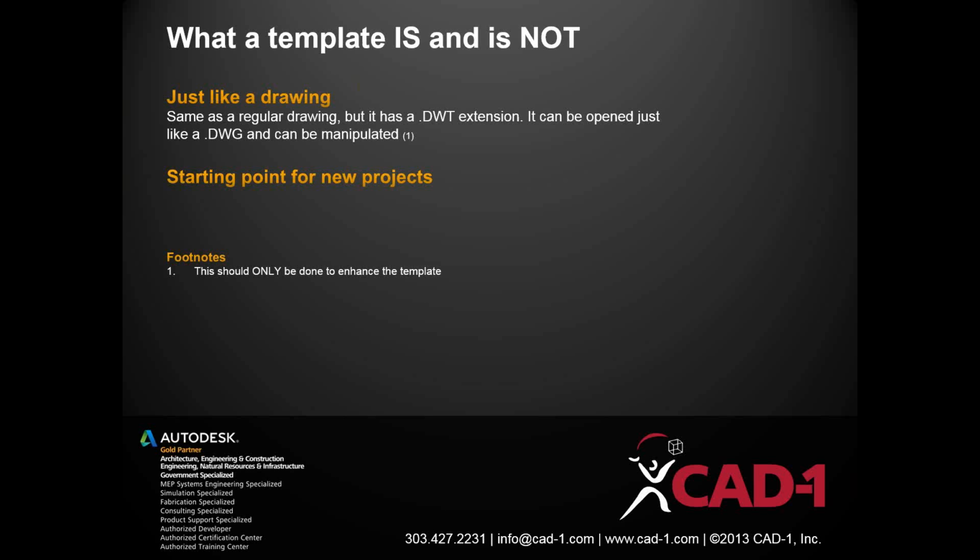Now, the reason that we want it as a template, a DWT, as you're going to see here, is that if you're doing this properly and if you're using templates and you create a new drawing, the program will copy the template for you automatically to start a new drawing. You don't have to open a drawing, do a save as, erase everything, and that becomes my new drawing. You just hit one button and you've got a blank, brand new drawing with everything already preset for you.